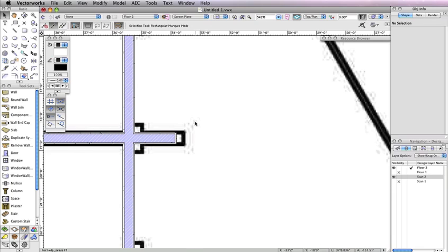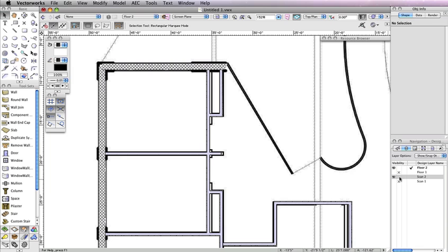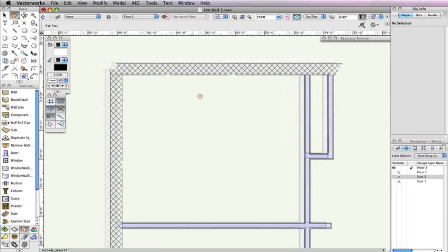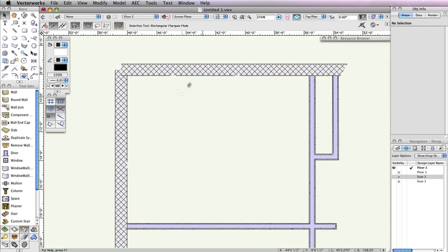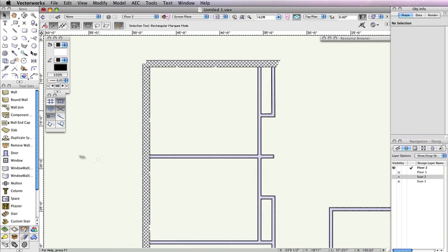Now, let's clean up the wall some before we move on. First, set the Scan To layer to Invisible in the navigation palette. If you look closely, you'll see that some wall breaks in these walls that are from the first floor walls do not apply here. So, select the Remove Wall Break tool from the Building Shell toolset and draw a marquee around these areas to remove the breaks.